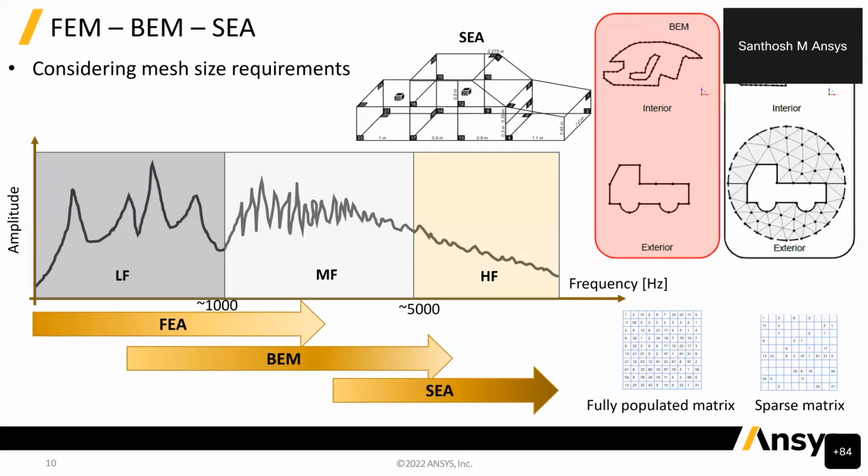Then there is a mid-frequency range where the resonances of the system are relatively closely spaced, where again, as I said, as we go for the high frequency, the element count becomes very high. That's where we typically use the boundary element method.